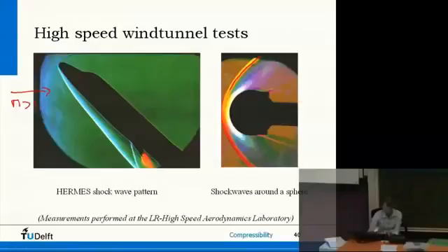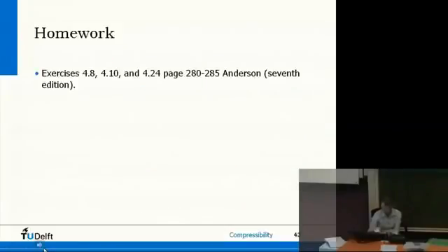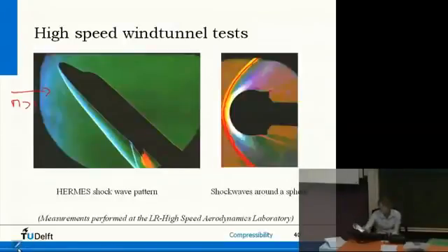thing. So if you put a pitot tube, do I have a picture? No. So if you have a pitot tube inside your supersonic flow, you might even have a shock here. So then you don't measure actually what is going on here in your supersonic flow, but you disturb your flow such that you have a problem. So we use different ways to measure supersonic flows. That's more in the compressible aerodynamics class next year.